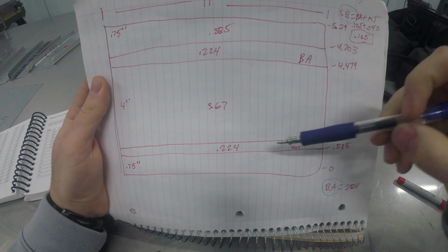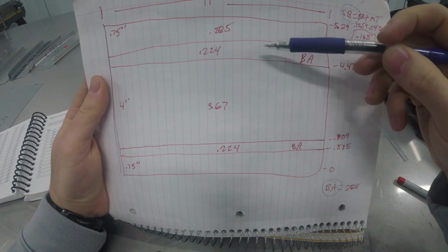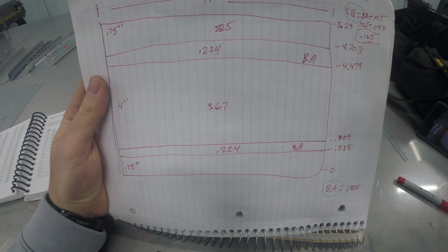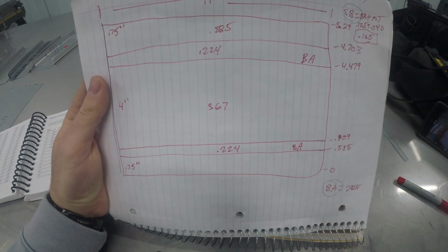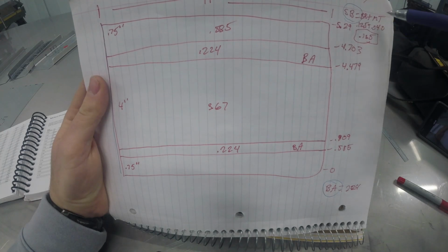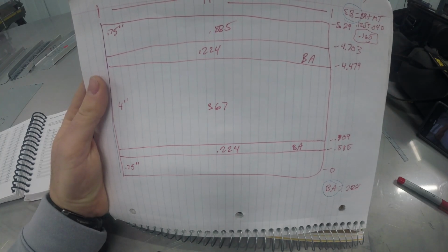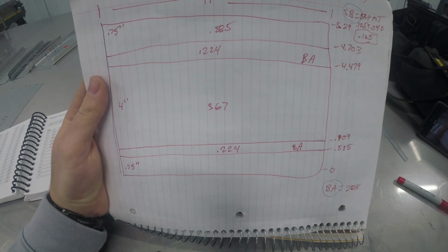Next thing we need to figure out is what our lengths are actually going to be when we take our setback away. Setback is your bend radius plus your material thickness. You need to take that away from your overall lengths here. So our setback is going to be bend radius plus material thickness. Your bend radius is 1/8 inch or 0.125 plus 40 thousandths, because that's the material thickness that we're using, which brings our setback to 0.165.